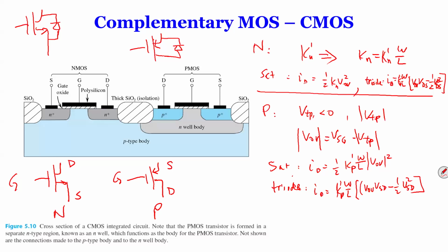You see, that diode is going to prevent current from flowing in this direction. But current can flow in that direction. Even if the MOSFET is off, like the main body is off, current can still flow through the diode. So that is a problem with a lot of MOSFETs. They have a body diode. Sometimes we have a body diode.